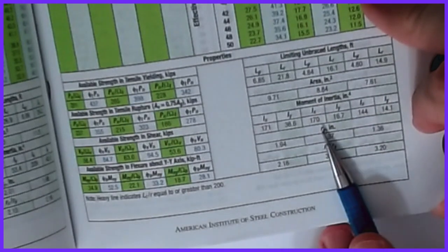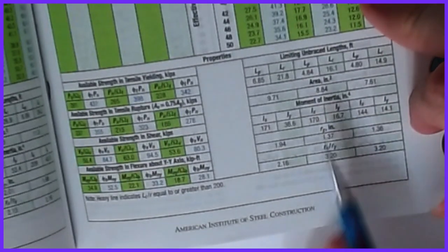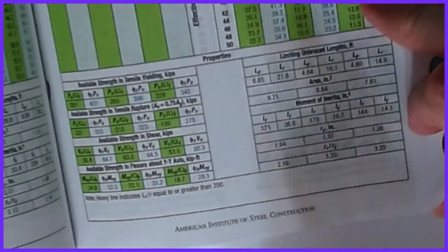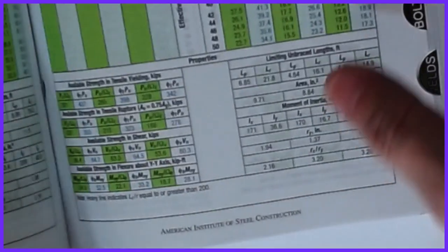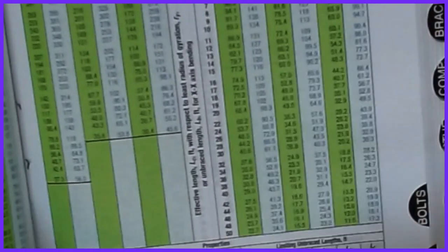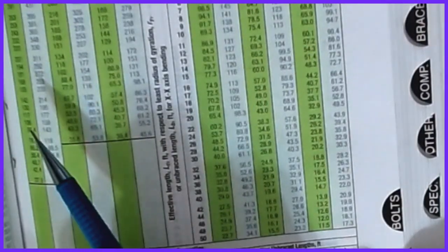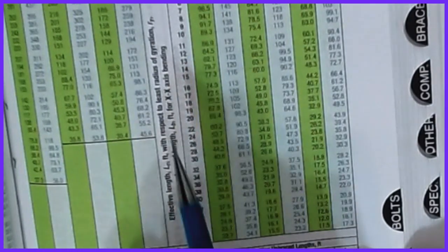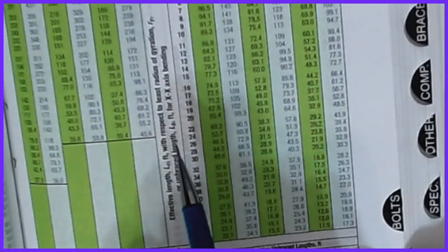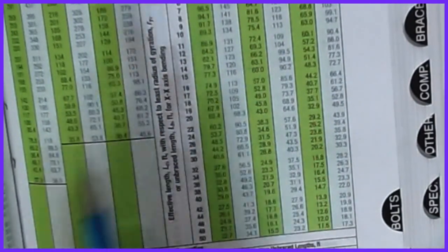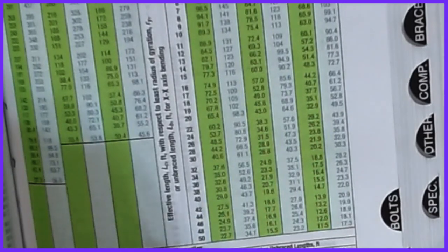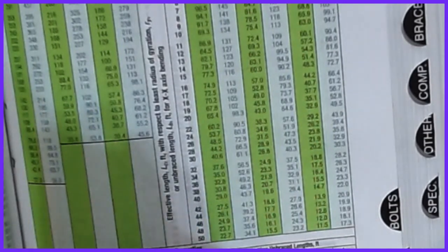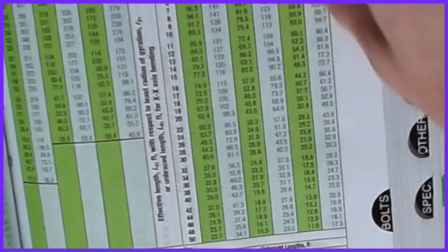And then we've also got our RY, or radius of gyration with respect to the Y direction, and you've got RX, RY in order to correct the table, because just like with the column tables, they've tallied the axial capacity, the phi PN value, based off of the least radius of gyration. These are KLY tables. So if your weakest direction is actually the X direction, you have to modify it and come up with that KLY equivalent, which was the RX-RY ratio that we talked about in an earlier episode. All right, so these are all nice and handy to have.